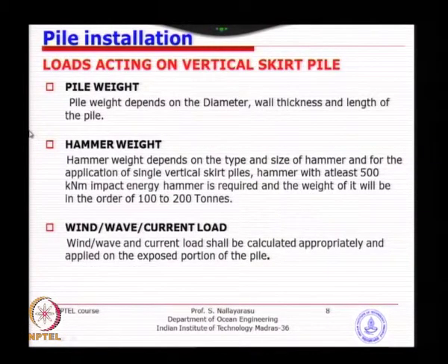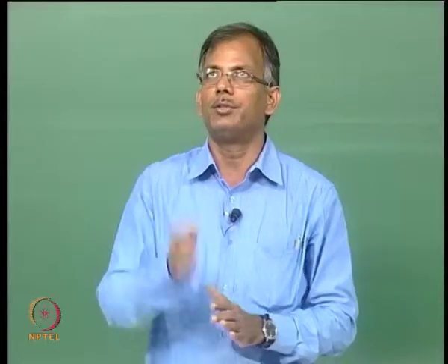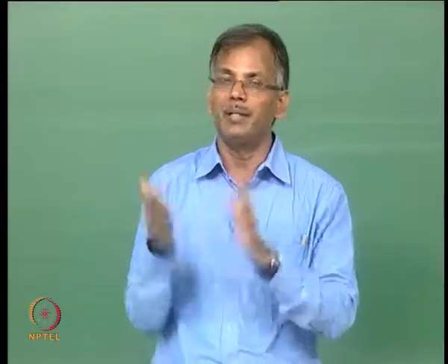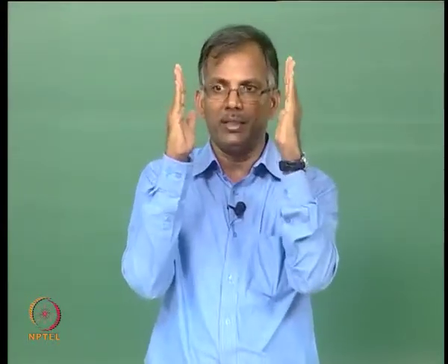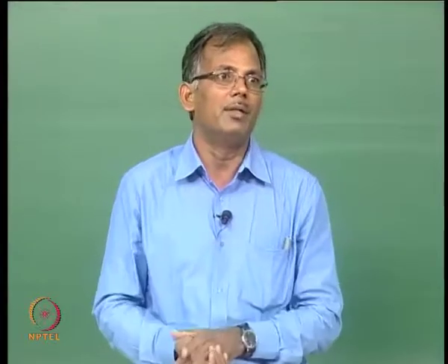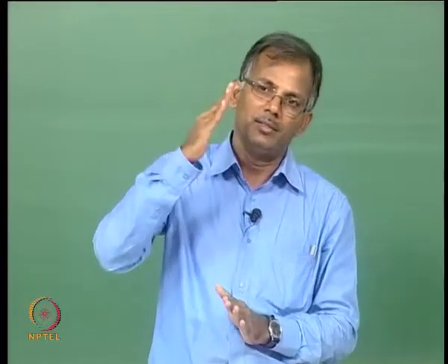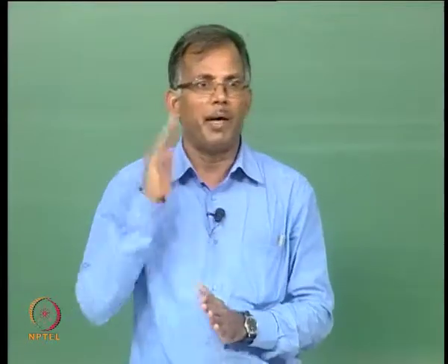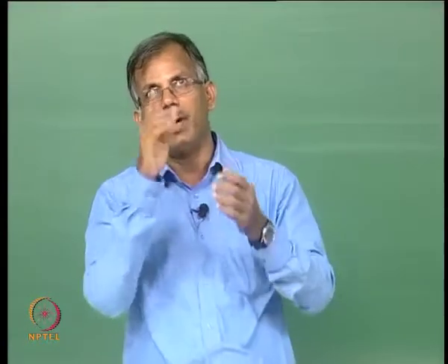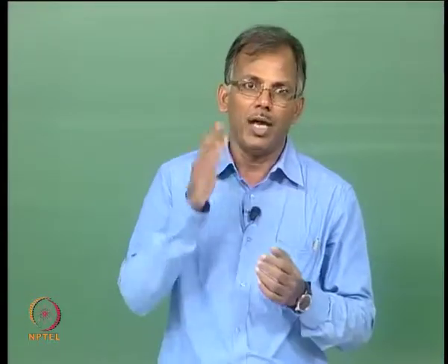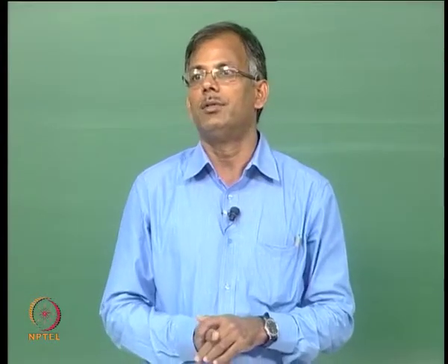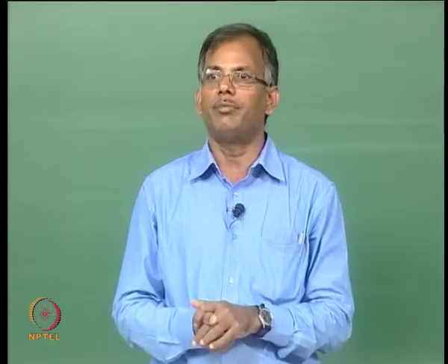So, what are the loads acting on the pile? Basically, it is pile weight itself. For example, if you have a vertical skirt pile, nothing to worry, because hopefully there is no external environmental conditions making the pile to tilt. If the pile is vertical, then it is an axial load to the pile, is it not? But if you have an inclined main pile or skirt pile, what happens is the weight of the pile is not anymore an axial load, it actually creates a bending moment at the point of support.